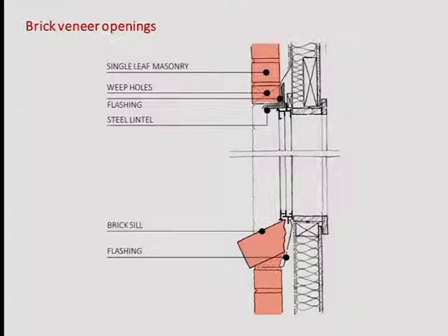When you want to create an opening, this is what happens. You puncture the wall, so you create discontinuity in structural terms and in terms of waterproofing. So what you need to do is simply to restore that continuity. And the structural one is restored through the use of lintels. In this case, there is a steel lintel here, and there is a plate there, and the seal.